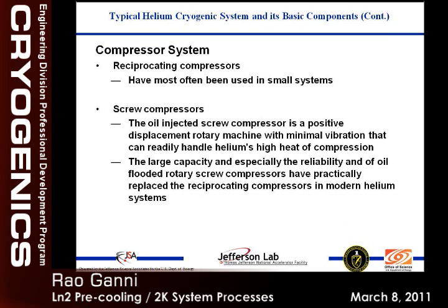In the past, originally we started with recip compressors when we had small systems, in the 1940s, and they used to break all the time. Because the specific heat is so high, they used to get so hot, and we used to inject so much more oil into it, and the oil is not that easy on the recip valves, so the availability used to be very poor and limited.